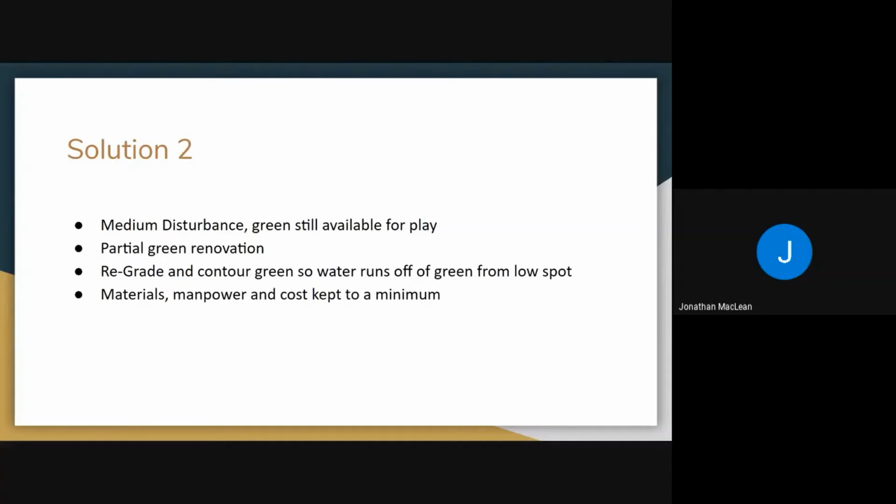excessive thatch buildup. Once the turf has been removed, the use of a small Sand Pro machine with a front blade, along with hand tools, can be utilized to reshape the surface, allowing the grade to be lowered, eliminating the possibility for water to be contained on the green. Using the builder's level during this process is vital to ensure 1.5% is the minimum drainage, and that is from Brower at the Golf Course Industry magazine.